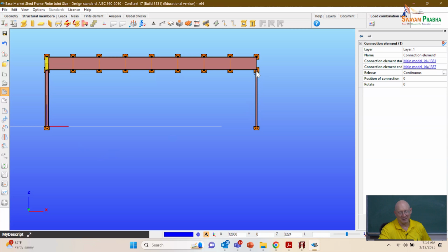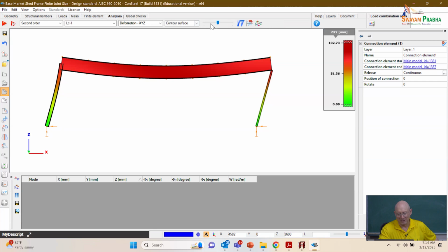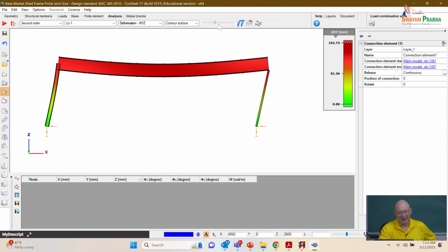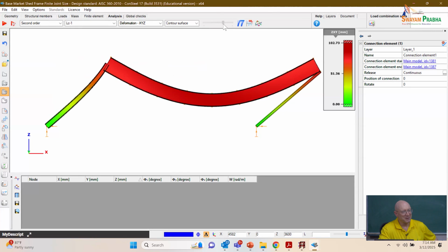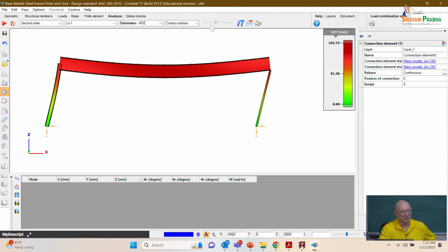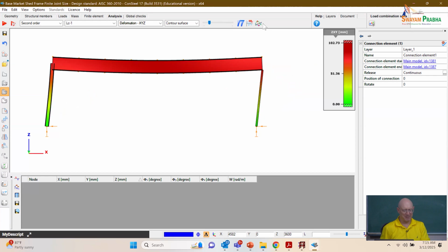So okay, here in this representation, we're just modeling the behavior. That's working just as a pin and strut, right? We're not generating any moment in that HSS section. Got a nice, perfect spherical bearing connecting the top of the column to the bottom of the roof girder. Okay. And if we do the checks here on this, we basically find that things are more than adequate.